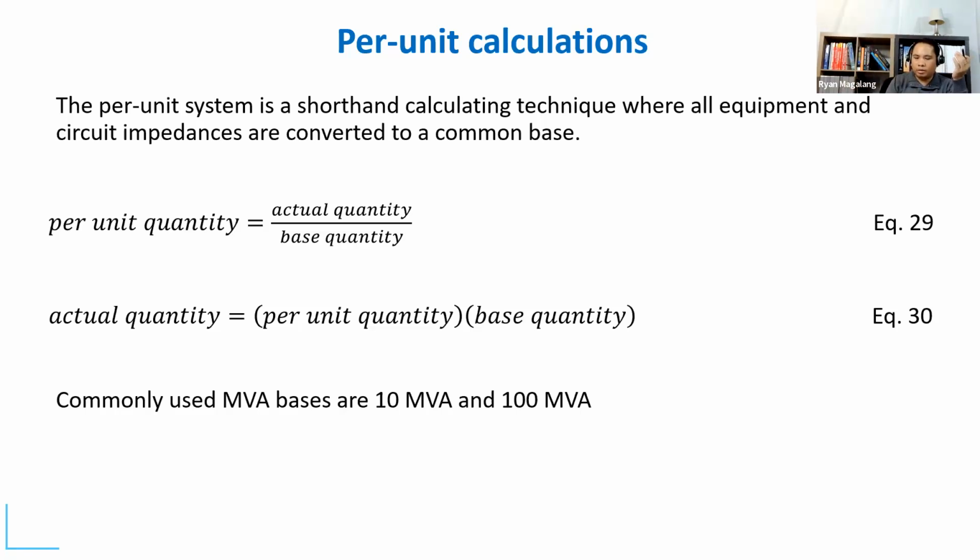So it makes it hard to calculate with all these transformations, and you have multiple transformers in your facility usually. So using this per unit analysis makes it easier. So you have to use a common base.